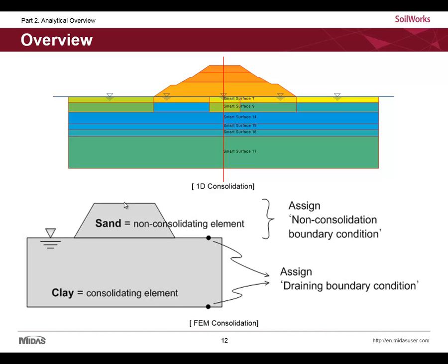Okay, so consolidation analysis is associated with drained and undrained analysis, and it is to calculate the process of dissipation of excess pore pressure. The excess pore pressure takes place in case the water resists external loading, so the reduction in excess pore pressure with time can result in the increase in effective stress.